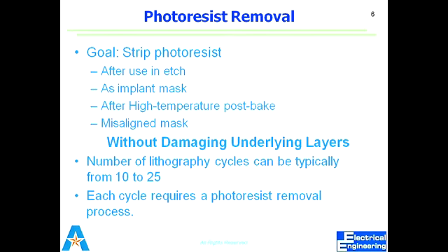Now I deposit the thin layer, a thin layer of metallic layer. It should be metallic in case of lift off. In this way, when I remove the photoresist, it will lift off whatever is deposited on the top of photoresist.